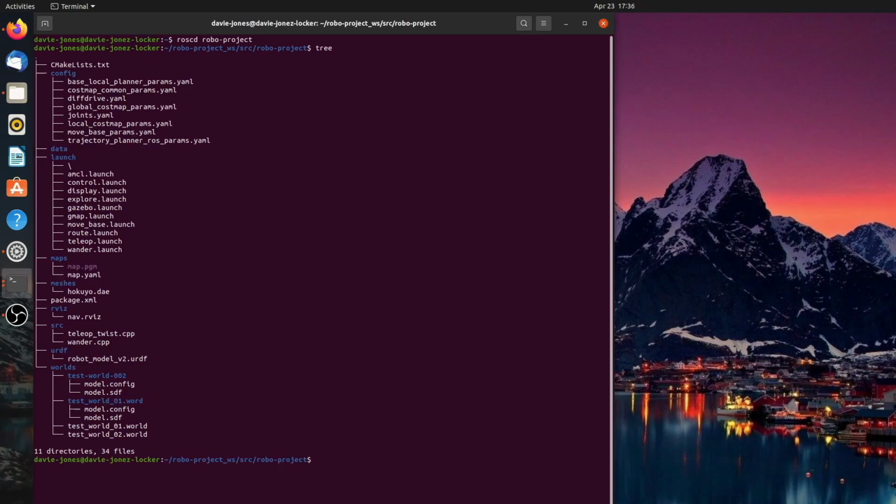This holds all of the YAML parameter files. These are needed for almost all the nodes. They configure each node specifically to work for the robot that I've created. Each one is used by the launch files and the nodes launched by those files to act according to what I need them to do.